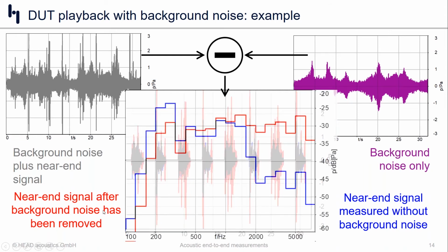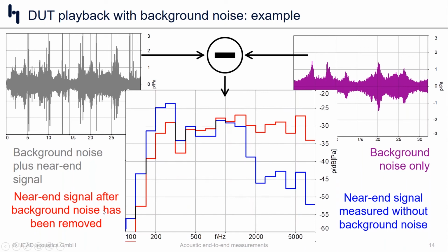And if we just look at these spectrums, not frequency response, but the spectrums of the resulting signals, so there's been no compensation for the speech signal input here, you can see that for a normally performing device, it's shown in blue, and when the background noise is triggering the processing on the device, there's all kinds of content being added above about 1500 hertz, and there's somewhat of a reduction down at the lower frequencies.